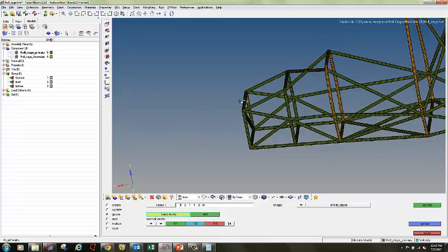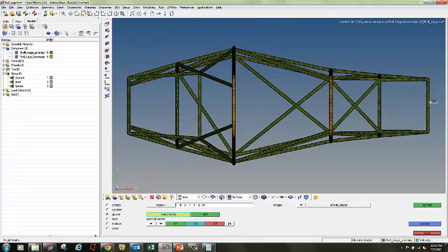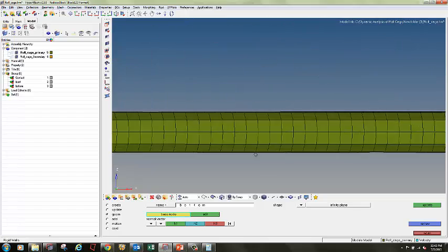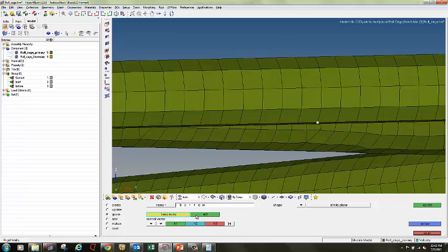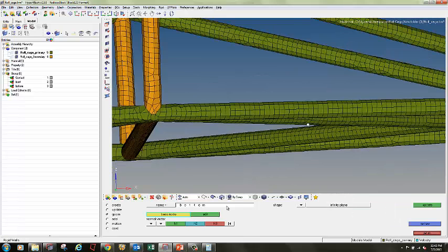So deselect the initial node, this one, and we'll create one more node here at the bottom, edit. This time I want the node to be in the Z direction but minus Z direction. So I will enter minus 346 and return. Again I can pick the direction as Z because Z is in positive direction. So I will click update.